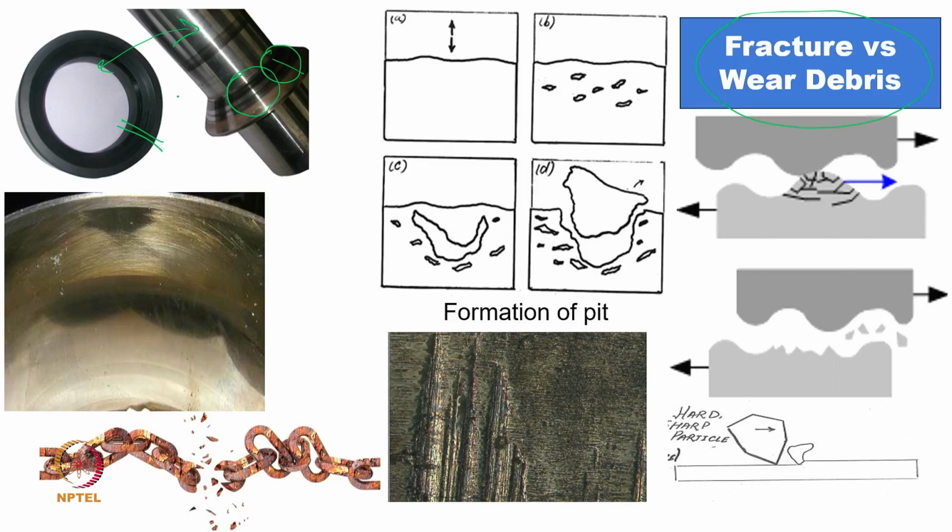So, material is getting transferred, that is the additive mechanism, and then over the running in presence of water, these particles also will get removed slowly and another layer will come. So, what is happening? One is the material is getting transferred and finally it is getting removed from a surface, and fracture is something like, if any material is getting detached from a surface, I can name it as a kind of fracture. Now, look at this bearing also I have shown earlier that there are a number of scratches on this.